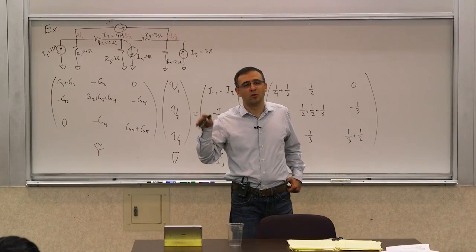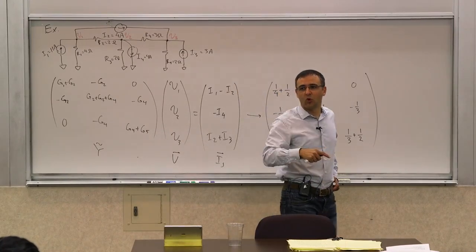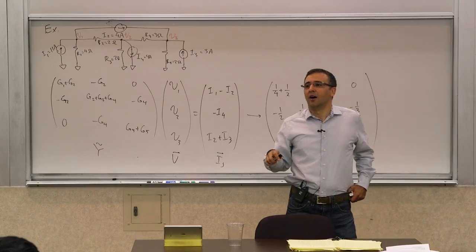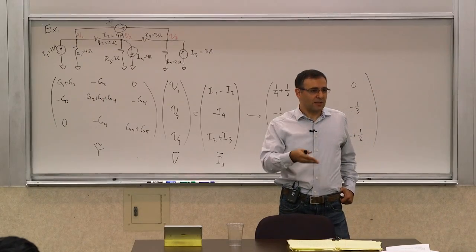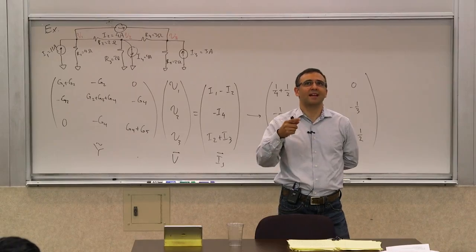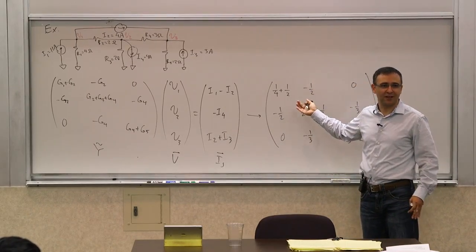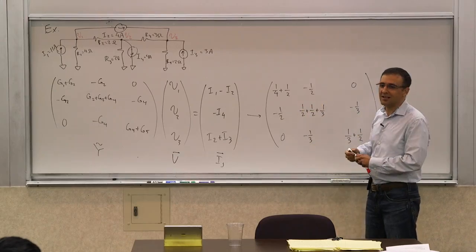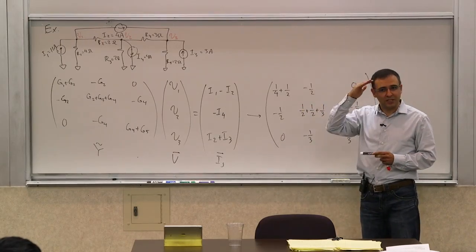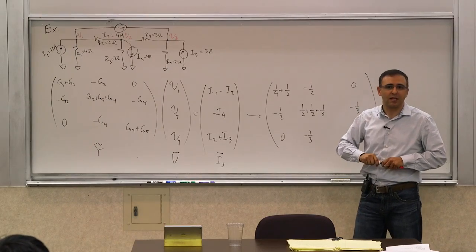Or millimho, or the older literature uses mho, which is an upside down ohm, also a backwards ohm. But you need to keep the units. Sometimes when you're writing a matrix, carrying all these Siemenses doesn't make life easier, so we say everything is in Siemens for now and keep track of it mentally. But in general, it's a good habit to have the units there.